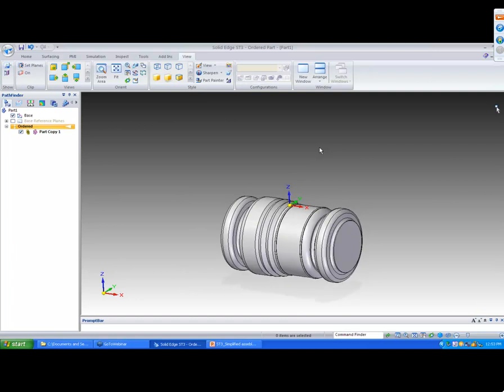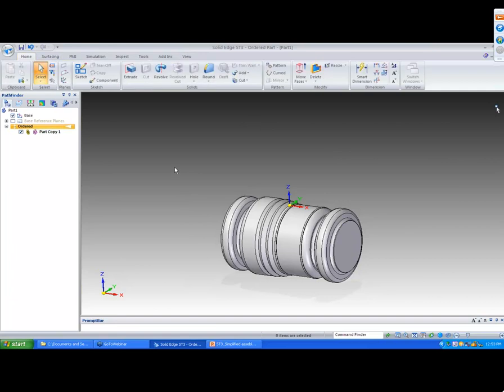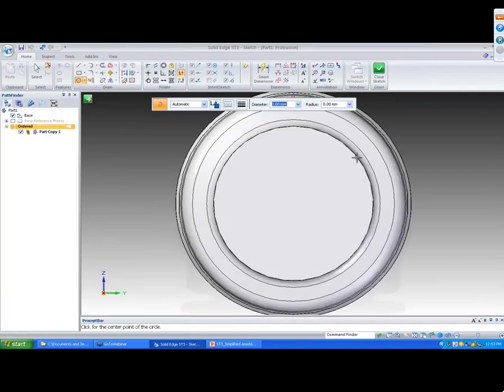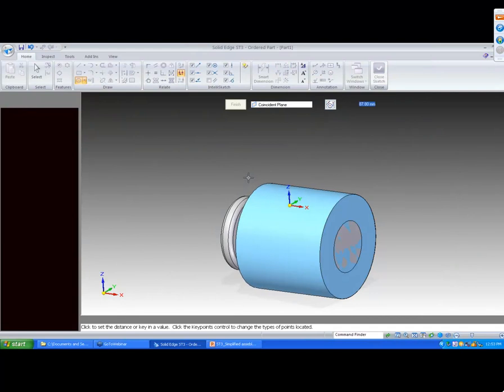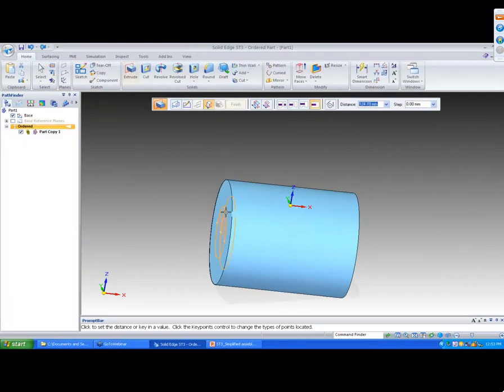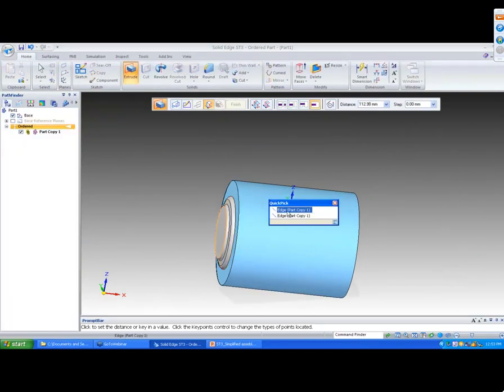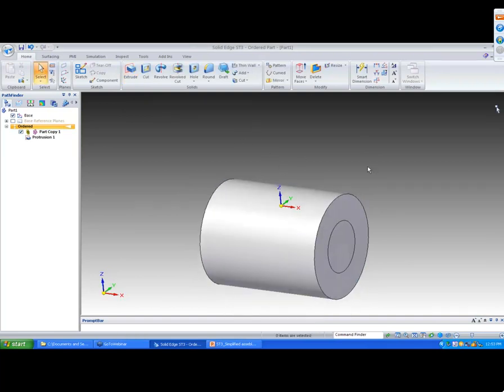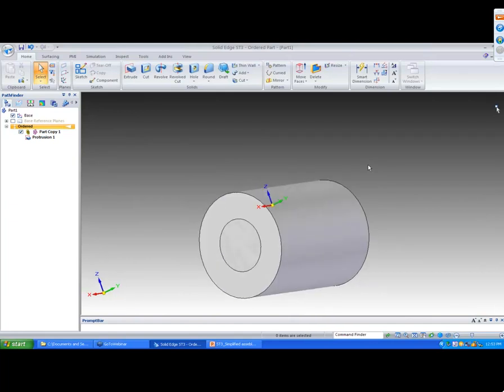The reason why I want to bring that as a construction body in this scenario is I want to create a female member, like a mold, out of this part. So what I can do is create a small extrusion on any end of this part. Say here, I'll give it a diameter of 100, and then I can give it an extent. As I'm moving towards left, I can use my quick pick to pick the extent, and now you'll see that it covers my parent body.